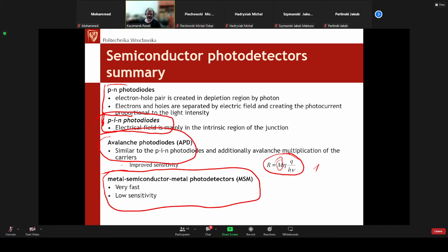And in fact, typically these APD photodetectors are somehow integrated with the power supply already in one, maybe not a chip, but some hybrid structure. Because the power supply voltage for such a structure needs to be at least a couple tens of volts, because it needs to be close to the breakdown voltage.